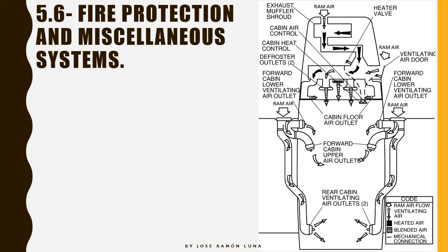Now, in order to ventilate the cockpit, the Cessna 172 counts on three subsystems, to say it somehow. We have the ventilation plumbing, the heater, and the air conditioning. These last two are also optional and may not be fitted in your aircraft. Some hot places need an air conditioning system fitted to the aircraft. Some others need a heater fitted to the aircraft. And in some other places, they just don't fit anything. That's just a personal choice. In this case, maybe it's a choice of your school.